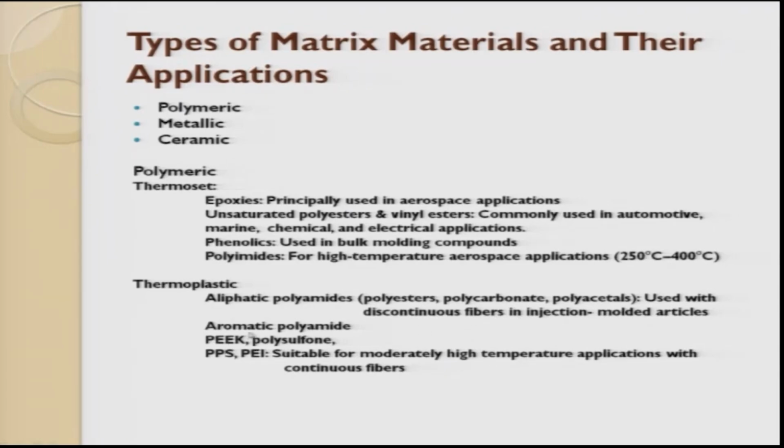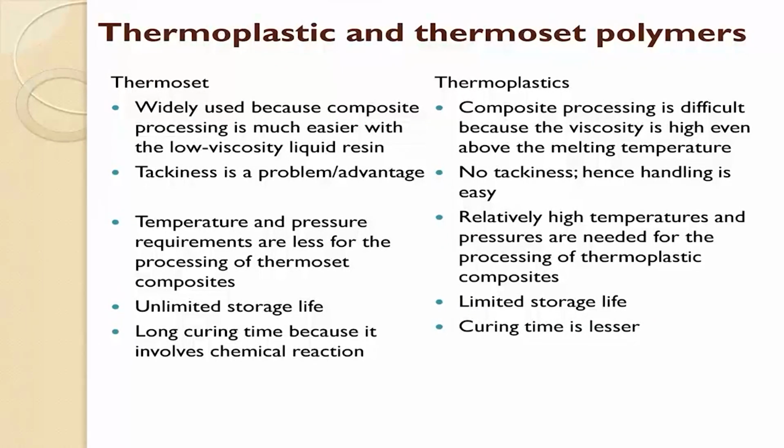You also have aromatic polyamides, you have PEEK, polysulfone, and then you also have PPS, PEI. All these things are used for high temperature applications. Now let us see the difference between thermoset and thermoplast. As you all know, thermoset is non-recyclable, thermoplast is recyclable.